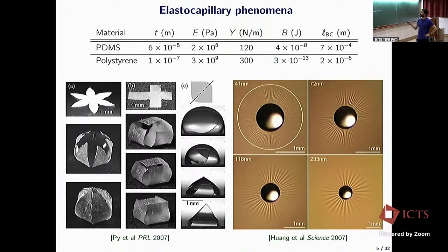Then when you look at the stretching modulus, so the moduli that are interesting for sheets are the stretching modulus, which are here. So these are comparable, okay? But then when you look at the bending modulus, the thick sheets will be much higher, okay? Because they have the same stretching and the others are thinner, so they have a smaller bending modulus. And from the bending modulus, you see that these sheets are in contact with liquid